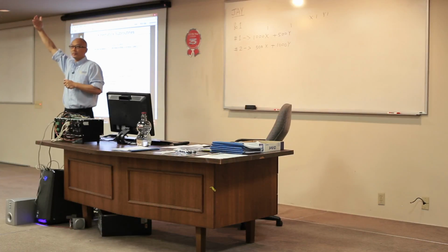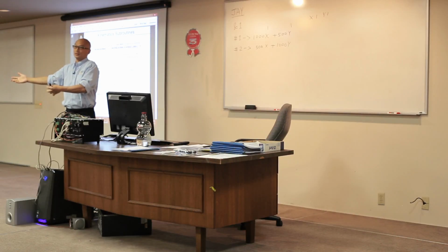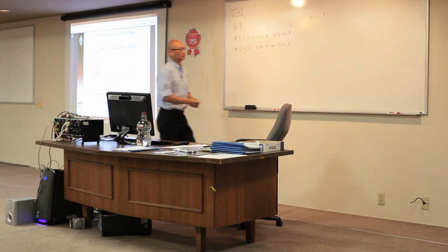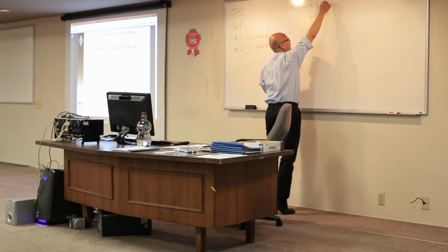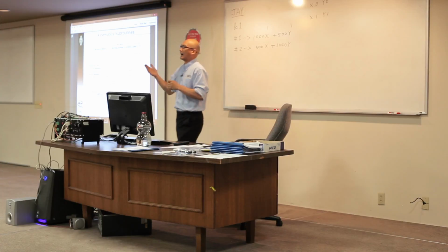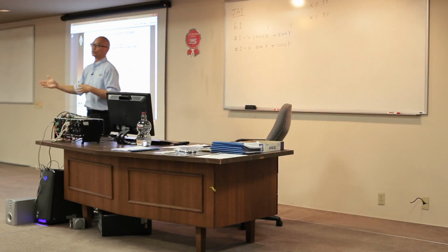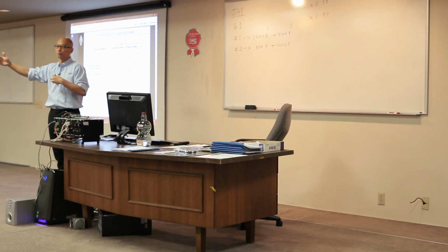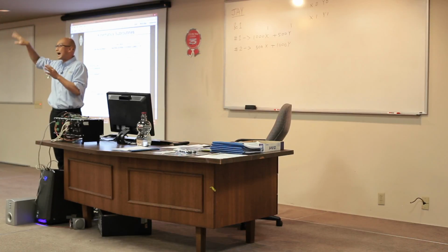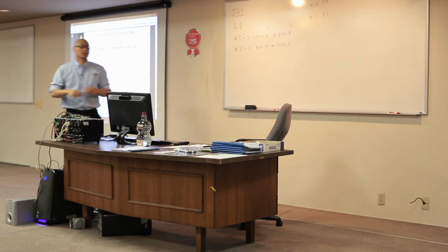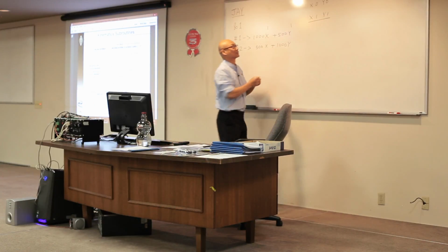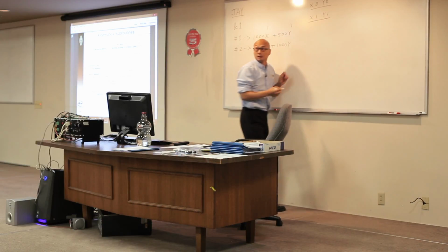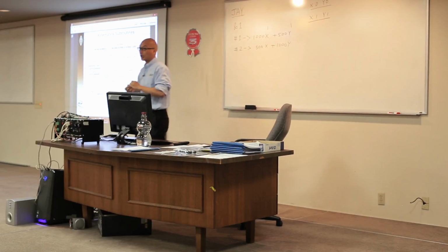But in the beginning of the motion program, I have to know where the axis is, right? PMAC has to use the motor position to calculate the current axis position before you execute the motion program, so I know for the first move how to do the trajectory. If this is the first command you have in the motion program, then PMAC has to know where you are right now through the current motor position.